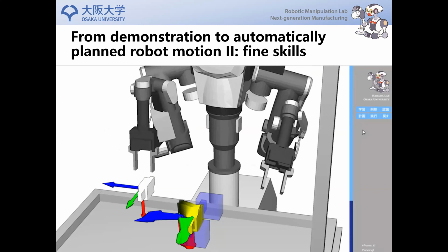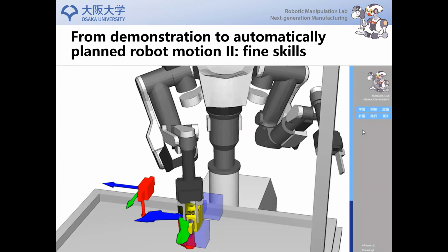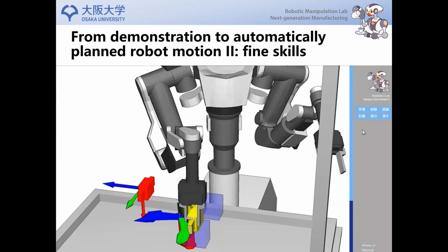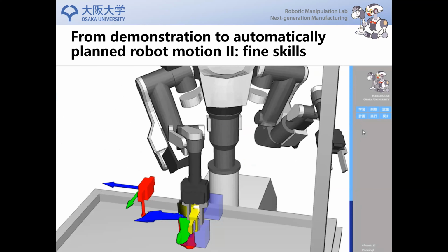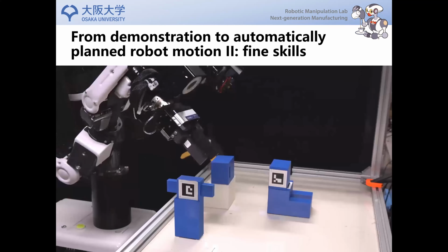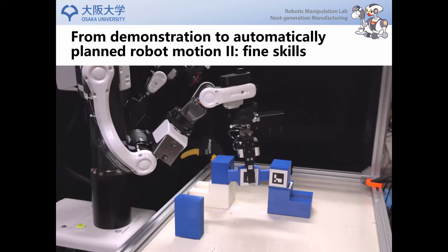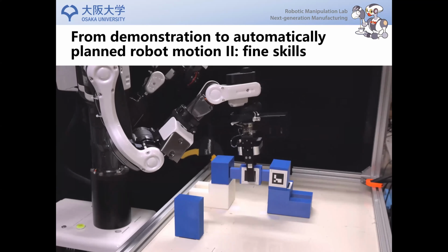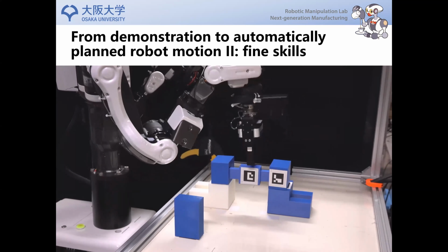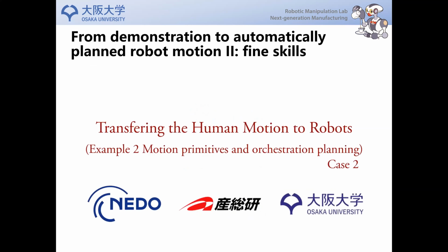We call this task a skillful task, and we cannot plan the linear motion directly or use the combined task and motion planning. Thus, instead of directly planning the motion, we record the whole trajectory, and then the planner plans the motion to the key or pivoting points of the skillful trajectory to realize the skillful motion.